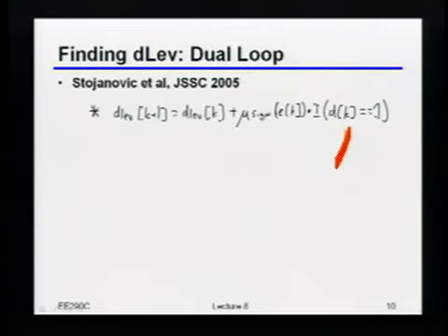The only caveat: notice that when I did this, I only had my updates when my data was actually a 1. So if I had really bad bit error rate and I was actually getting a lot of zeros when my data was a 1, then maybe it wouldn't converge. But the good news is, I need to be making mistakes about half of the time to not go in the right direction. My dither might be horrible, but to really not go in the right direction is pretty tough. So I'm sure you can come up with conditions where it would not converge, but for all practical purposes, if your link was going to work, it'll converge. But those are both great questions.